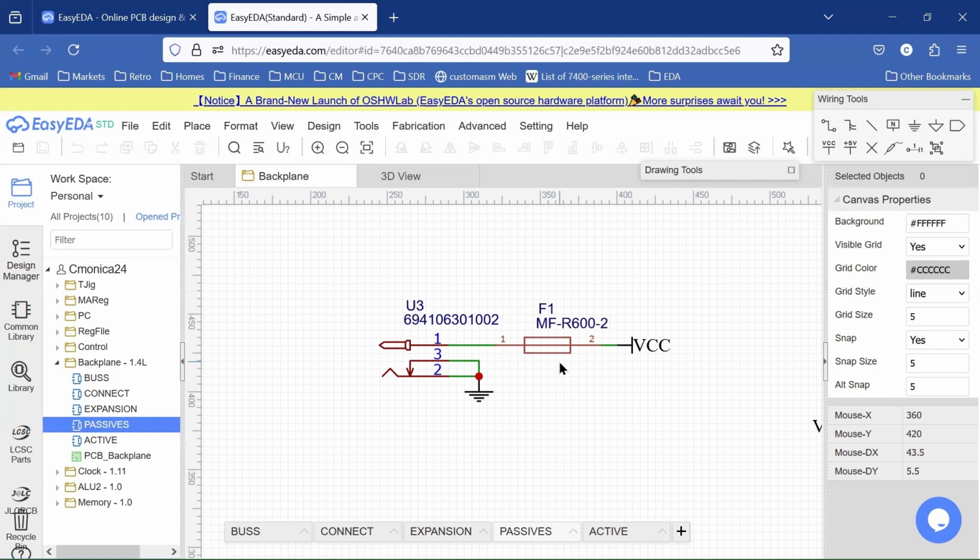The boards require a certain amount of power based on the components on them, and they draw that power from the power supply, and we need to ensure that it doesn't go over a certain number. For us, that's going to be 6 amps, and we're using the 6 amp fuse here for that purpose. So we just don't want to add extra boards that go over the 6 amp limit, because that's our design limit.